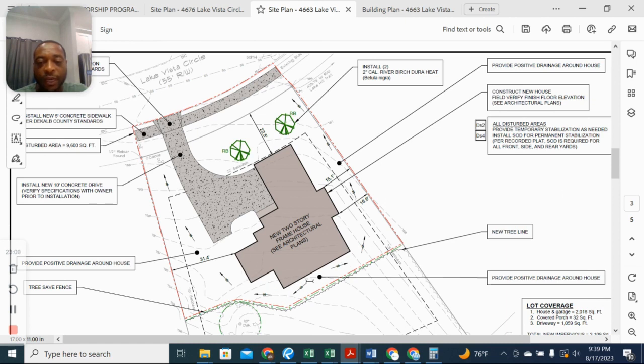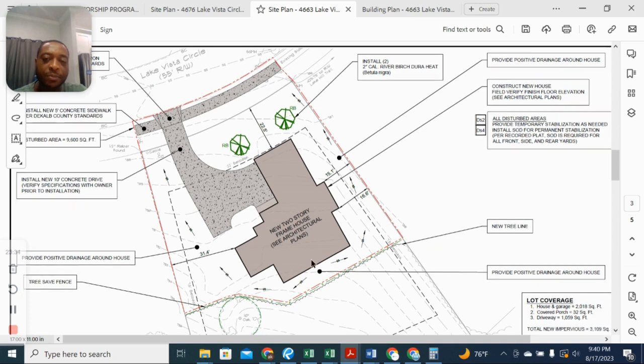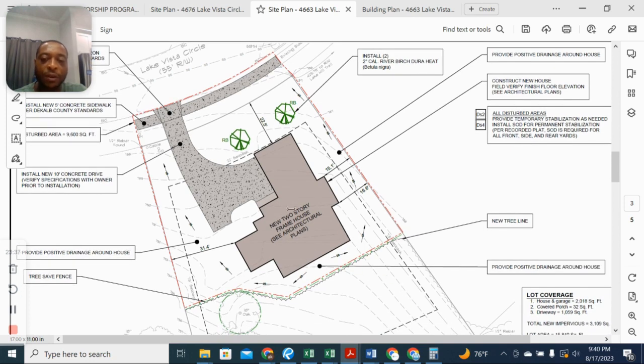We went from across here, it was 37 feet. We went from here, it was 4 feet. We went from here, it was 12 and a half feet. So we knew that we were well within the confines of our buildable area. We are there. And then we also knew that we were deep enough, but we definitely have plenty more space from the back of our buildable area. Okay, so the house, when you take the footprint and sit it here, it is there. What else does our site plan show us? It shows us our driveway, how our new driveway is going to go.